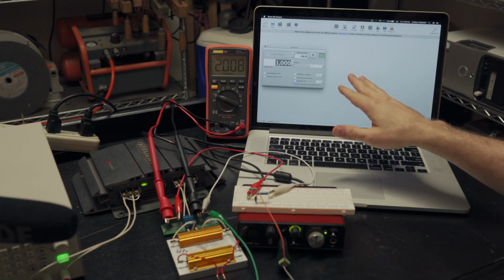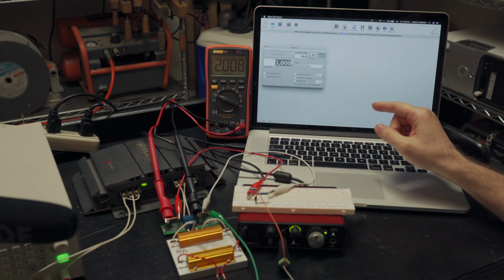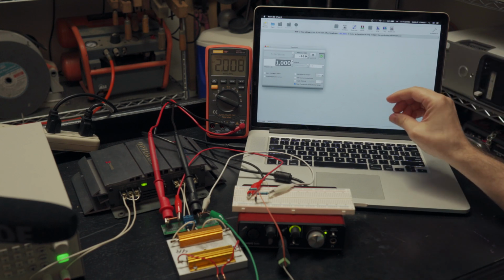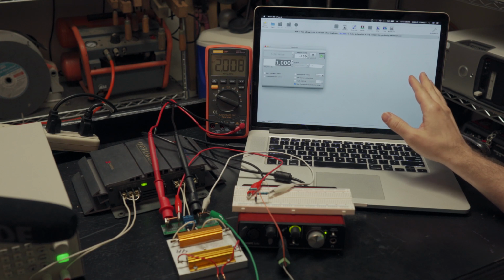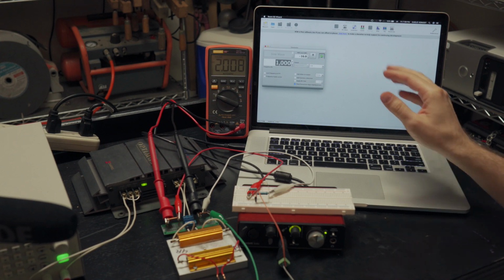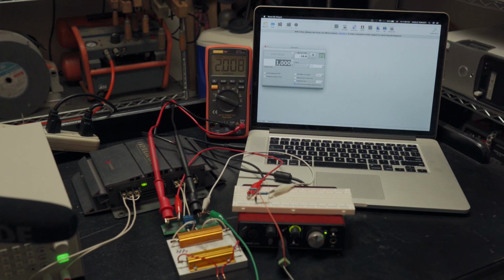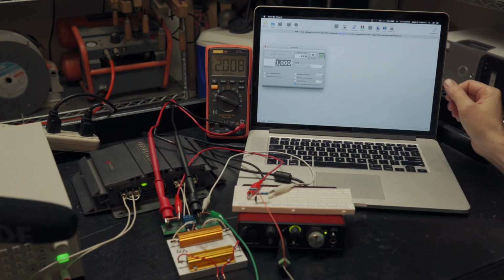And so now that we've done this, we can actually pull up the FFT. Now, here's another thing I should mention. This is not a replacement for an oscilloscope. And the reason why is because, I don't know if you remember the last video, but in the last video we noticed that our amplifier oscillates. It oscillates at some large frequency, 200 kilohertz or something like that. And it rings up there, at the same frequency it oscillates at, way up there in the hundreds of kilohertz range.